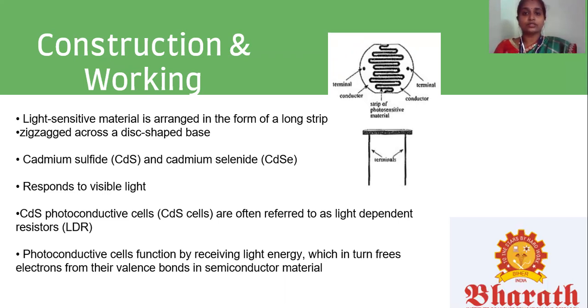This change in resistance may be large, several 100,000 ohms in the darkened area to only a few hundred ohms in the sunlight. Embedding the conductive path within the semiconductor substrate in a zigzag pattern will enhance the level of the resistance. In addition to the increase in dark resistance, the same pattern will reduce the current as well as change the output current to about a milliampere.